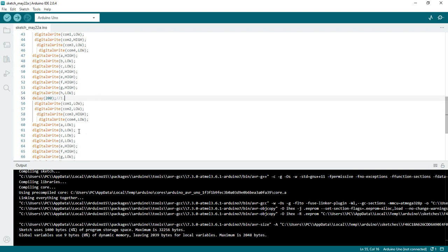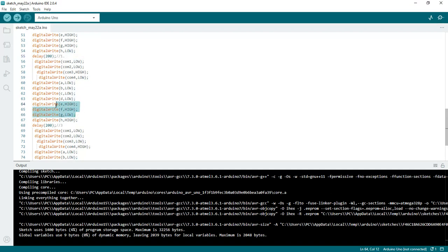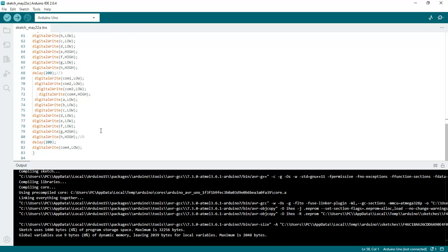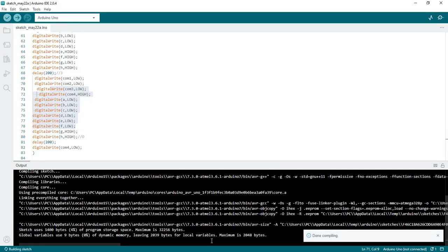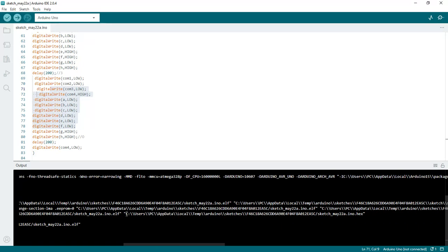So I make sure the second digit has the dot, and for the third digit I'm expecting 3, so I'll make the third common pin high and the other 3 common pins low, and the fourth digit, which is 0, again the equivalent value I'm displaying here. Now compile this program and link up your hex file path with the hardware design. So this is your hex file path.